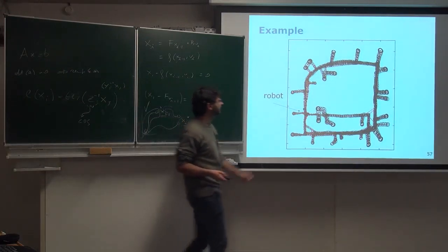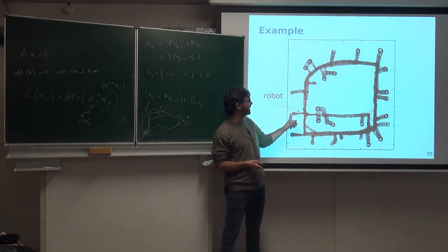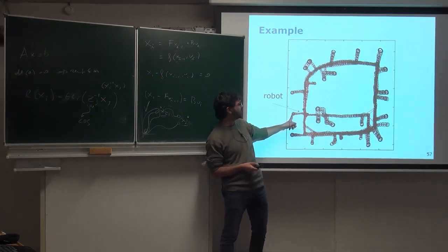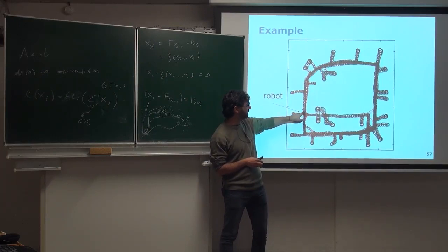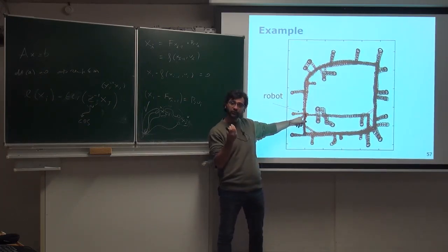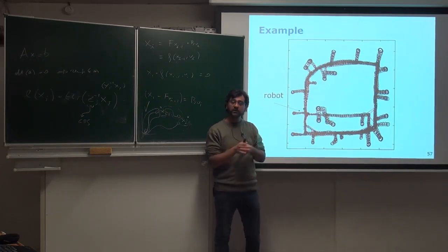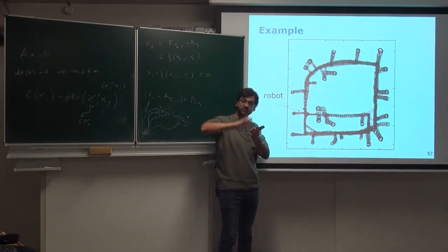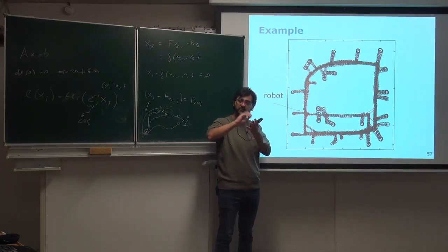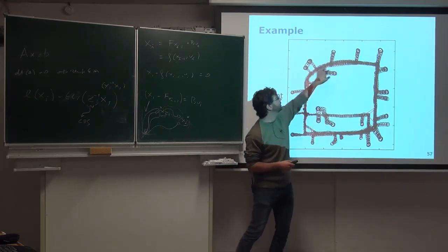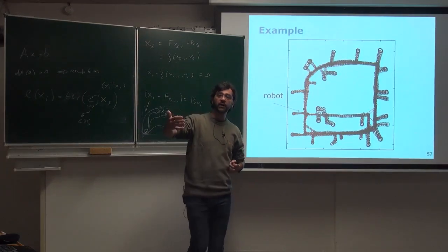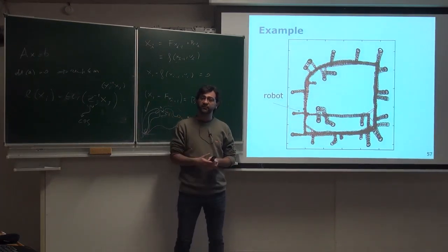And what you can also say is that if the robot is here, you can see the 95% ellipsis. So I think these are the 2 sigma ones, so it's not 95, it's 94 something. And basically this means that all these poses here might be useful for data association, where the robot is searching for these observation-based constraint measurements between the poses that come from aligning the scans. But we don't need to do any scan matching with all the remaining ones because they are statistically too far away. So we can just eliminate them from the data association search. Okay?